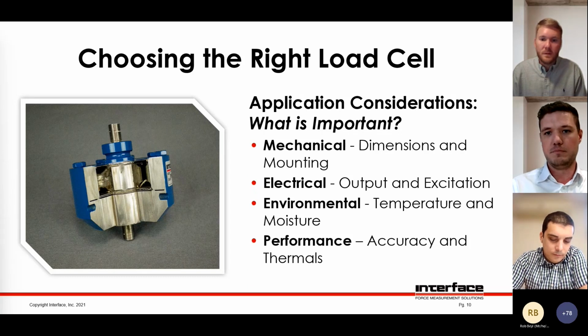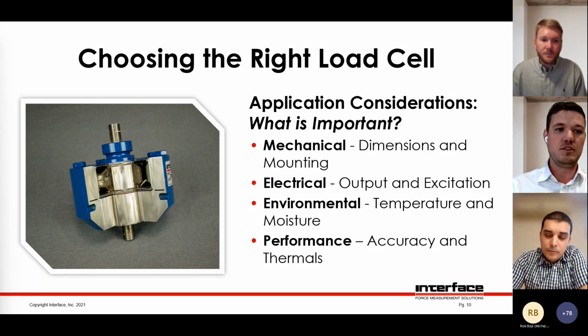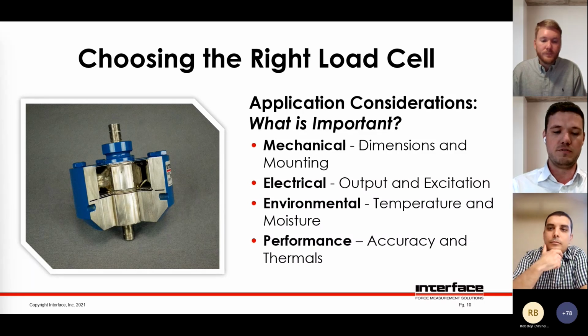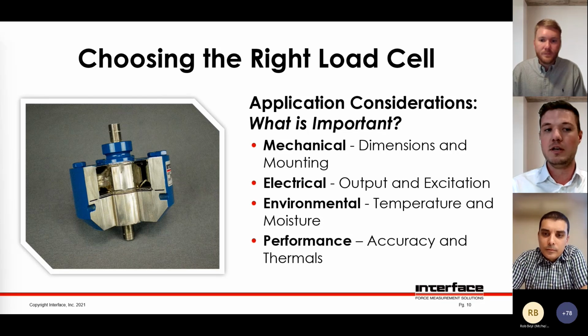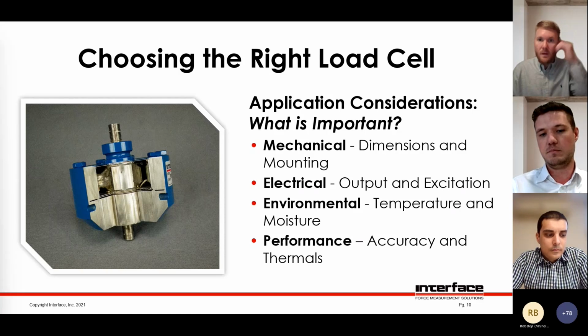But then there's also mechanical considerations, dimensions, mounting. Is it going to be threaded? Is it going to be a load button? Are they going to be rod-end bearings? We could also consider the size of the load cell. Will it fit into the system where it's being placed? Sometimes for the force that you need to measure, a very large load cell would be required and may not fit into a specific system. So we could look at a different form factor, like a column load cell, which would be longer and thinner, but still take a very high load.